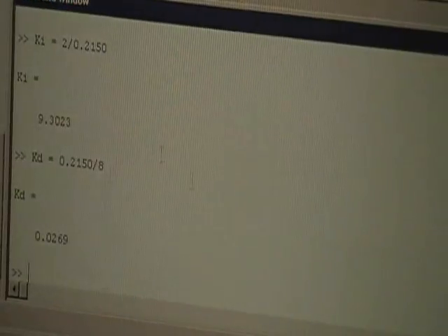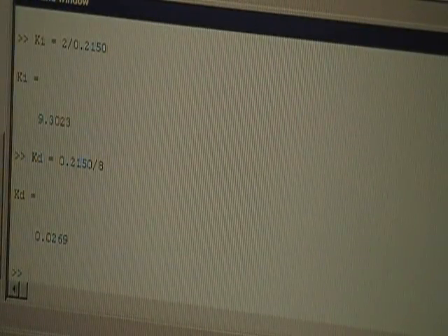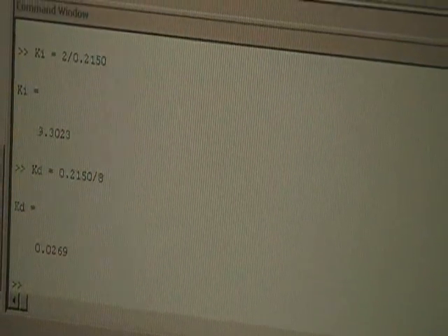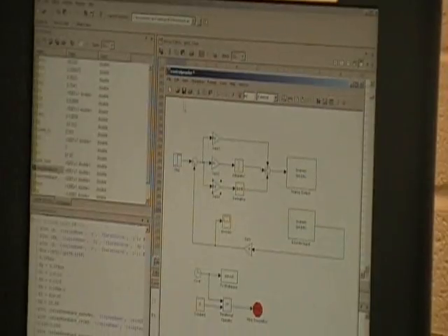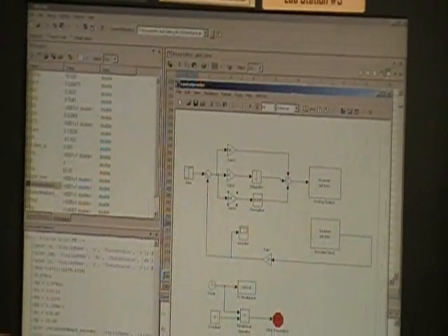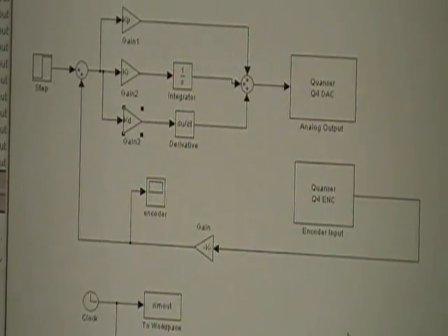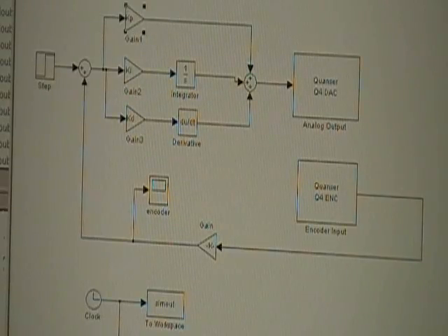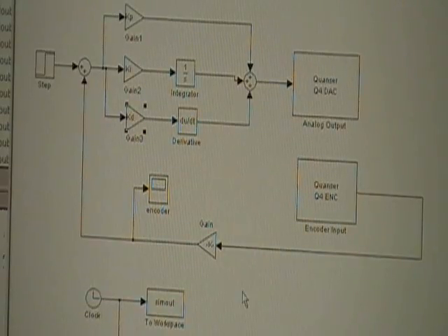So after that, you just go and make a plot. That is going to look like that. So this is the Simulink model of the controller now. And then this is going to be KP. You just put KP here, or you can write a number if you want to. Same for KI or KD. Just run the program.